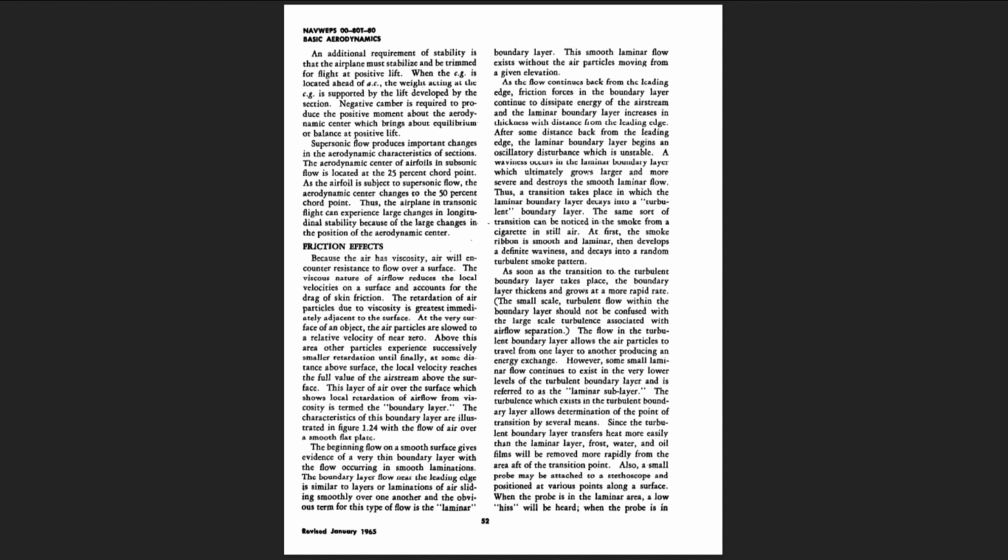Friction effects. Because the air has viscosity, air will encounter resistance to flow over a surface. The viscous nature of airflow reduces the local velocities on a surface and accounts for the drag of skin friction. The retardation of air particles due to viscosity is greatest immediately adjacent to the surface. At the very surface of an object, the air particles are slowed to a relative velocity of near zero. Above this area, other particles experience successively smaller retardation until finally, at some distance above surface, the local velocity reaches the full value of the airstream above the surface.